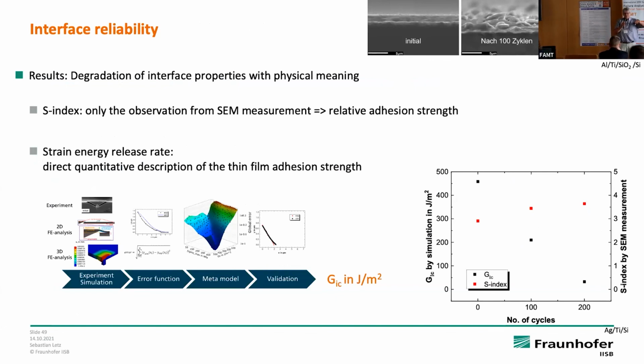It will be spread over the whole device. And what we do is we have about a 50 hertz signal, heating, cooling, heating, cooling, and during this time the thermal energy will propagate. So I think it's not limited by the microscope itself or by the video camera. It's limited by the material. And the deeper it is, the more it's blurred.